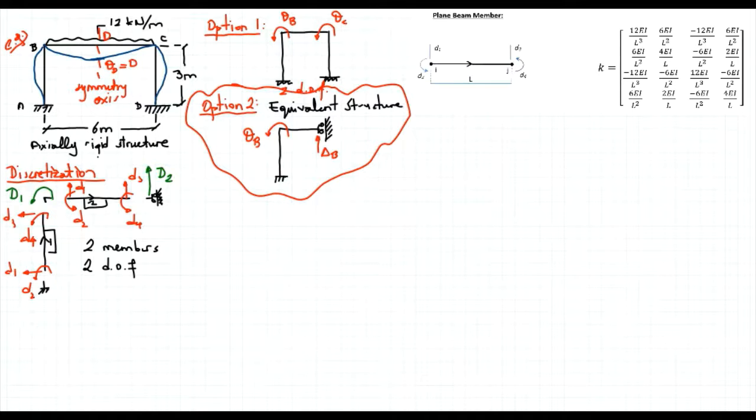Now, after having said that, we can determine the force vector. Remember that in order to determine the force vector, we do superposition. So that's the equivalent structure. We have uniformly distributed load here, that's a fixed support, so no deformation, all degrees of freedom are equal to 0.